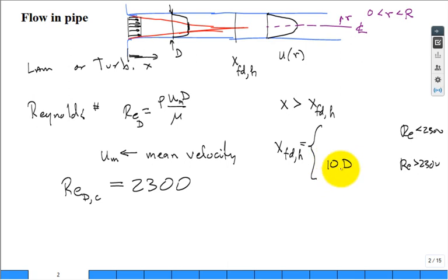And that's one of the things you should never forget out of your fluids class, and I'm reminding you now because it's very important out of this class. If you go down 10 diameters in turbulent flow, basically no matter what disturbance you had, like the entrance into the pipe, or maybe going around the bend in the pipe or going through a valve in the piping network system, you will get back to being fully developed if it's turbulent flow in the pipe. And a lot of problems in engineering applications are turbulent.